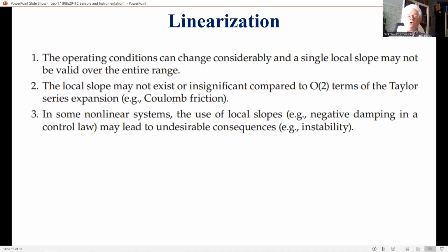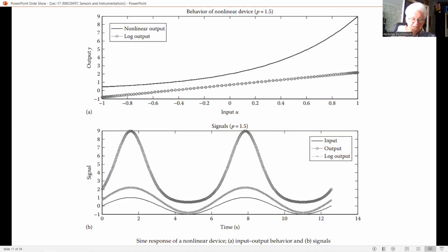So, several other methods are available to reduce or even eliminate nonlinear behavior in devices. They include the use of calibration curves in the static case, linearizing elements like resistors and amplifiers in bridge circuits to neutralize the nonlinear effect, and nonlinear feedback. A significant consequence of a static nonlinearity is a distortion of the output. This can be linearized by recalibration or rescaling.